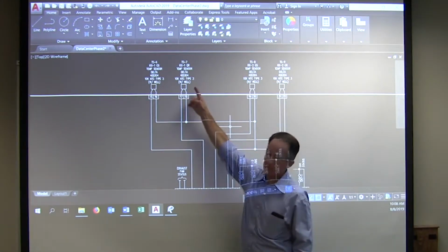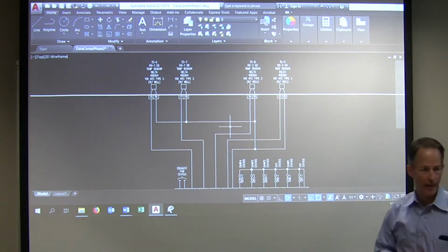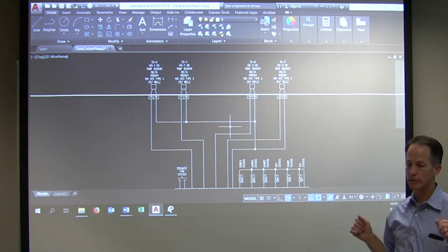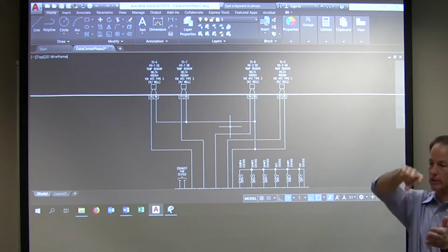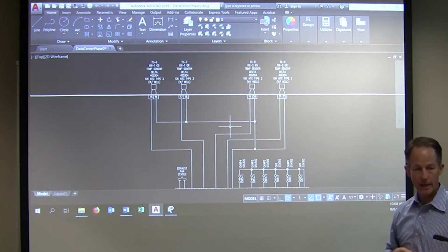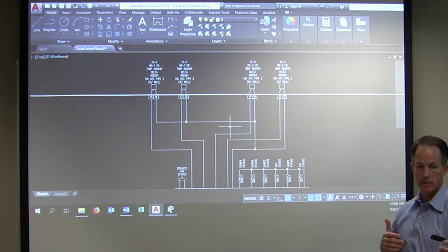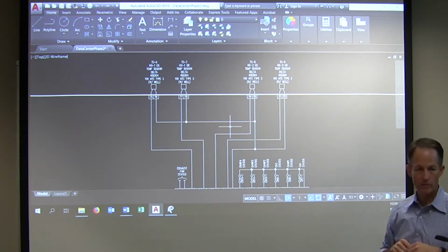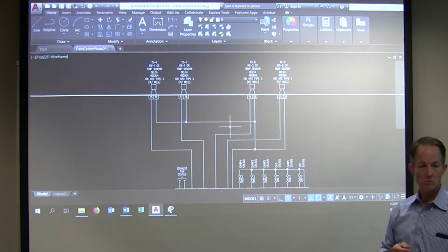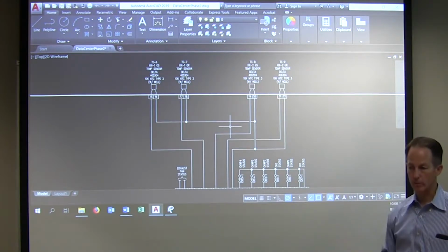But one of the things is I have 10,000 ohms sitting out at the end of that wire. How much resistance is 400 or 500 feet of wire going to add to that overall resistance? Because if it's the wire plus the thermistor, that's my total resistance that the controller sees. So if I've got 18 gauge wire and I'm running, say, 500 feet out to the sensor, which is a pretty long run, 500 out, 500 back, following the electrons, what's the kind of resistance we could expect on that length of wire? And I'll give you a range. Is it 2-3 ohms, 20-30 ohms, 200-300 ohms, or 2,000-3,000 ohms?